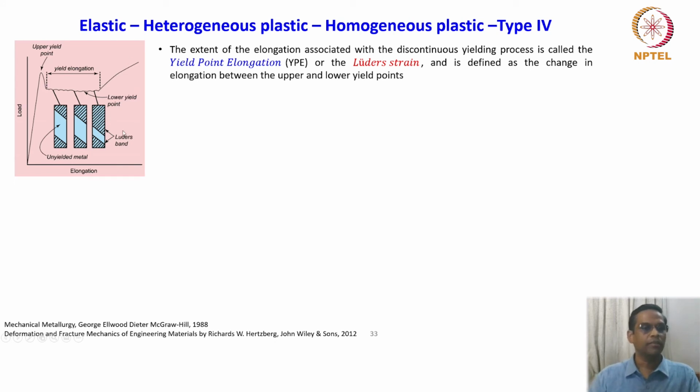discussion. Here is the same stress strain diagram in a much more elaborate manner. Here the point of interest is, I just want to show from the B to C in the previous plot. It has got some elaborate description here. After the lower yield point, the complete band is called yield point elongation. How this Luder band propagates from the point B to point C is nicely shown in this